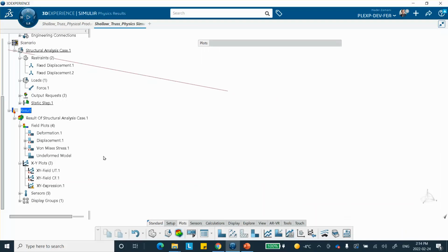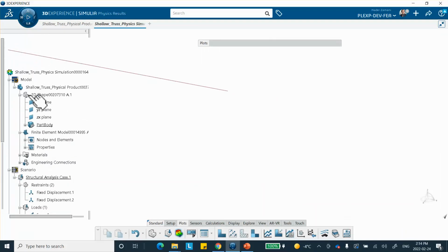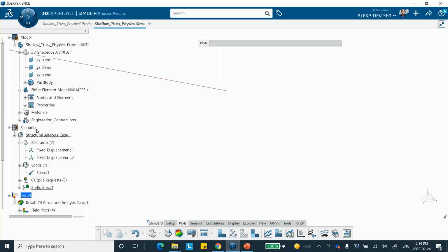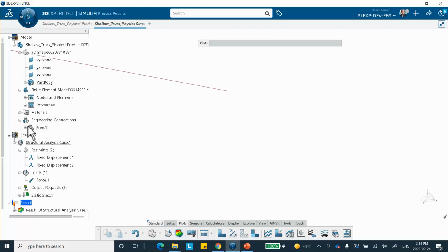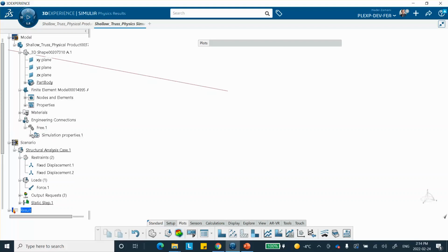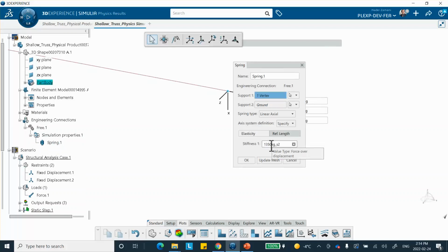And just to convince you that we're going to have a problem if I put those restraints and the load on a point, I'll let you do that, but I want to show you something else. If you go to the spring here, we're going to change the stiffness of the spring. If you make it too small, essentially you're trying to make it approach zero, and it's going to bomb out. So let's make this thing, I don't know, 10 times smaller. 10 times smaller may still actually work, but we're going to see.